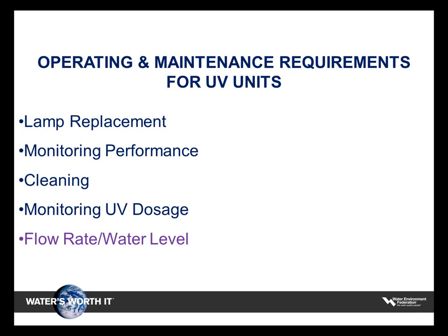Cleaning is another part of the system. It takes time. It takes manpower. The system has a self-cleaning mechanism, but that only does so much. Twice a year, we take our systems out, dip them in a dip tank, which I'll show you later, clean them with citric acid, rinse them off, and then put them back in.